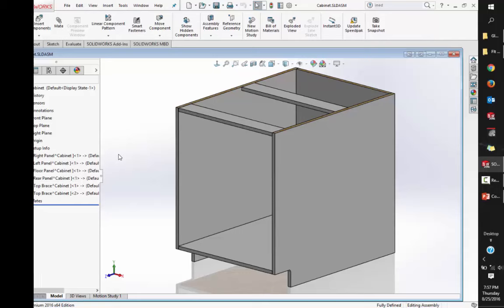So an easy way around it is once you import this assembly and you open up the assembly, take all the parts, right click on them, say make virtual, and it pulls all the data into the assembly, and you can literally take the part files and check them out. Now I have a full functioning assembly file that has all the parts embedded into it. I never have to worry about controlling those other items. Kind of make sense there? All right. If you go to the DASI Solutions website, there is a blog. I have a whole write-up of the steps involved with that and how it works. So you had a question, sir?